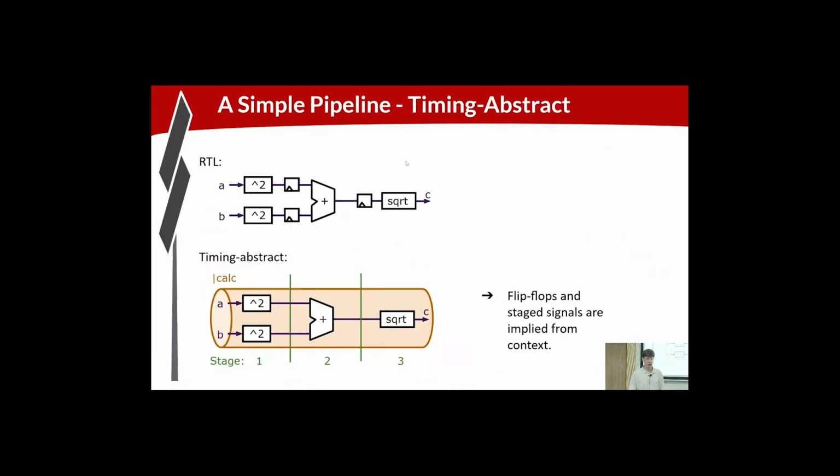So this is how we look at the pipeline logic, thinking about it in sort of an RTL mindset. When you use transaction level Verilog, you design your logic with a transaction level thought process. You give yourself the context of a pipeline, and the pipeline has pipeline stages, and within those pipeline stages you have logic, right?